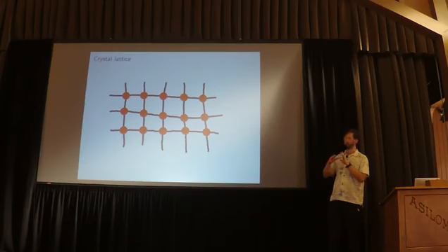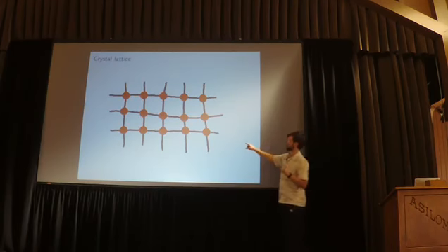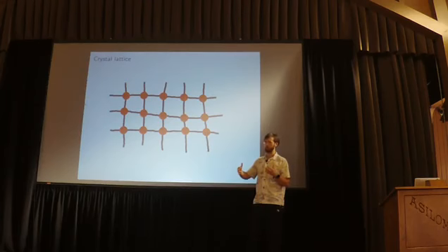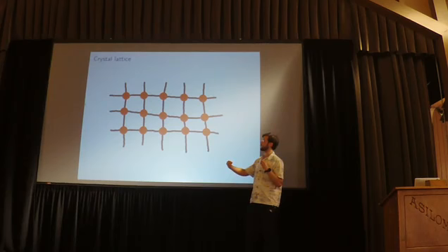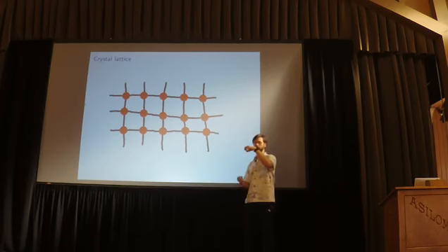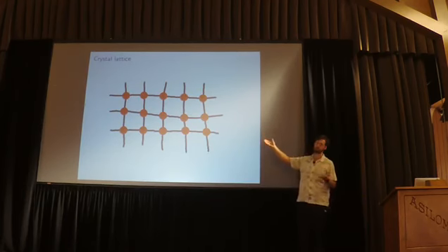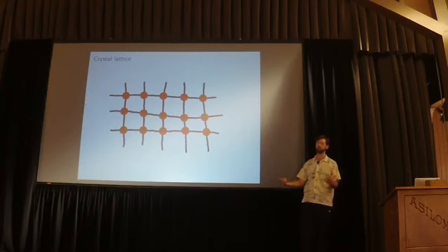There's an issue with how this crystal lattice is aligned with the actual part. You can imagine that if you were building a bar of material, the bar is going to be loaded longitudinally, in the long direction of the bar. You might want to line that up with a certain direction in the crystal lattice, and that's true for the materials we work on as well.